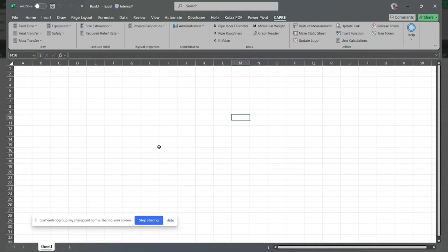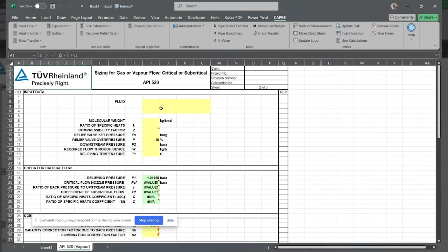So I'm going to press OK. But that's kind of set the default. Then I would open up my sheets. I can't do it the other way. Once I've got sheets open, I've started using it. If I change the units of measure, these values wouldn't change. So if I had 6 in here and I change the units of measure to bar absolute, that 6 would stay as 6. And that's just because we're in Excel land.